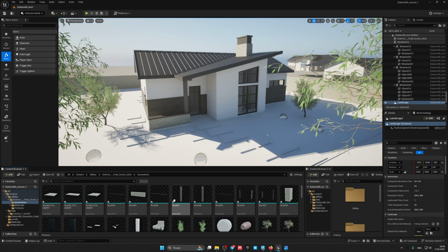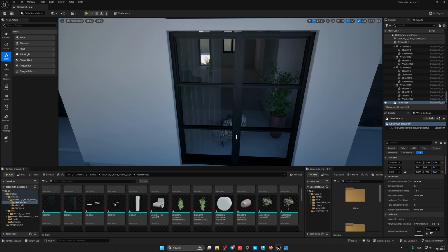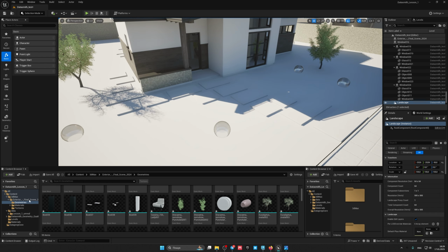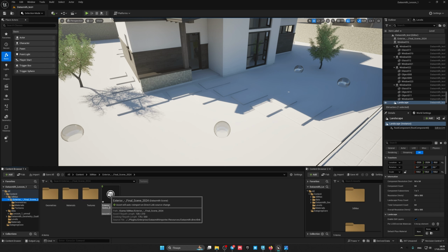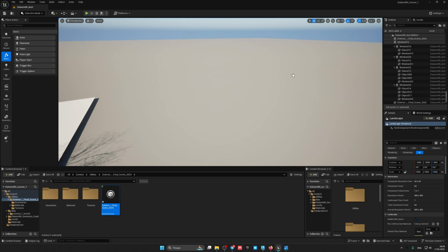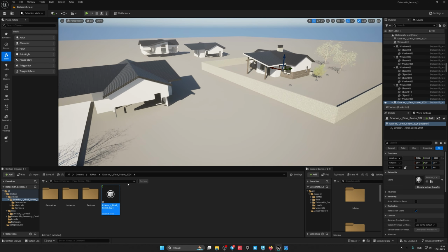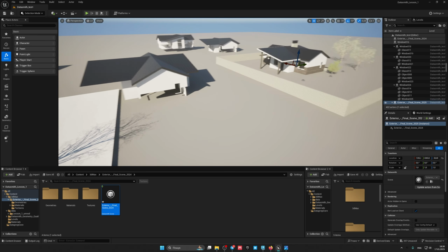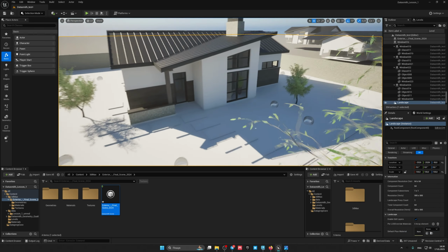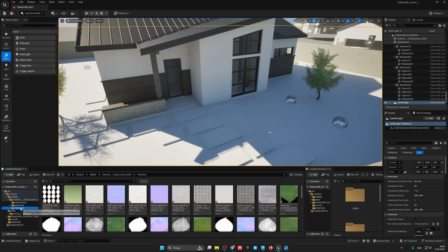Upon entering, we see that here separately, there are plants from the interior, chairs from the interior, pots, and so on. But going back up the folder, we have the entire container, and we can, for example, even extract the whole scene like this again. And we simply get a copy. So this is a container that includes everything that came from 3ds Max. I'll press Ctrl-Z. We also received materials. That folder with textures.